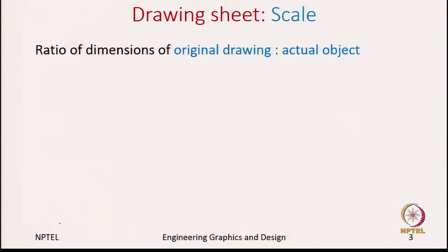So, what do we define by scale? We say it is the ratio of the linear dimensions between the original drawing and the actual object. So, here we have three options. Either we can do full size scale, which means 1:1.